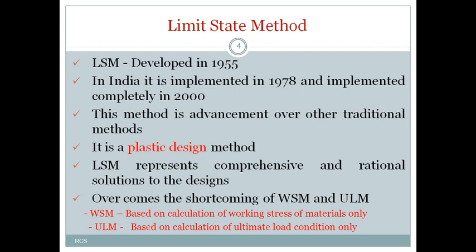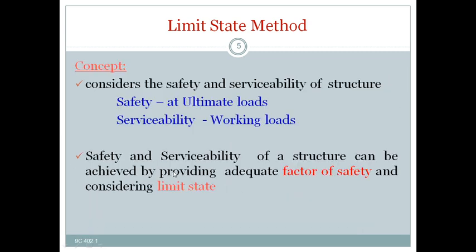How? Because we are overcoming the shortcomings of the WSM and ULM methods. As I discussed, the WSM, the working stress method, is based on the calculation of working stress of a material only, and the ultimate load method is based on the calculation of ultimate load conditions only. But this limit state method will consider both, that is the working stress or working load, and the ultimate load also. That's why this method will give comprehensive and rational solutions to the design.